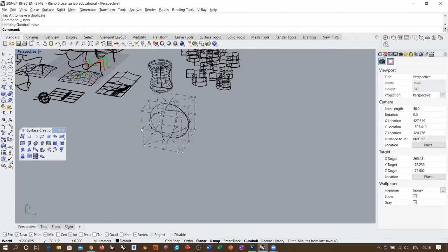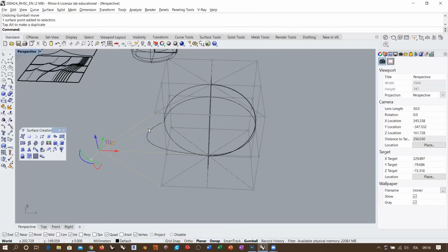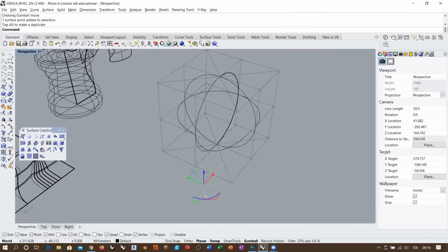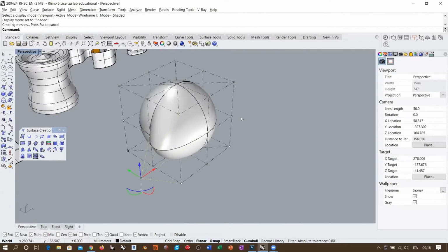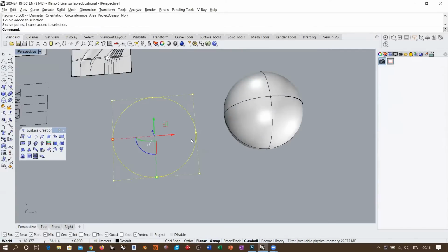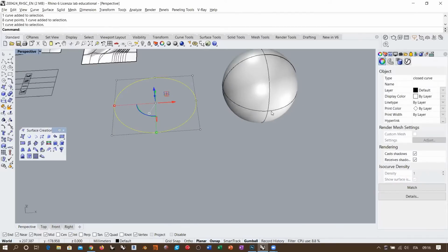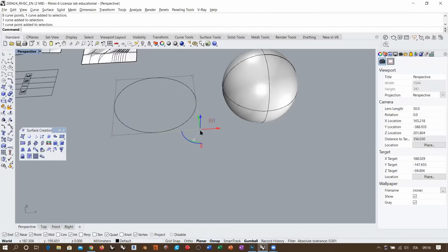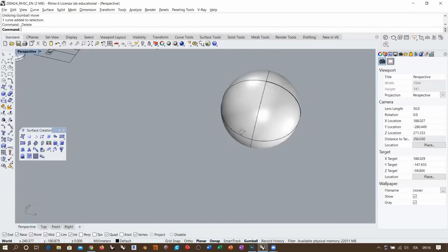So it has different weights for the points. In this case, for example, if I take this one, you see that I'm creating this kind of discontinuity. This is more visible if I do something like this. So you cannot deform it. The sphere is not a deformable object, and the same happens with a circle. If I create a circle, I see this square set of control points, like the isocube for the sphere. Whatever point I touch here, I produce a discontinuity along the curve. So it's an extremely rigid geometry.